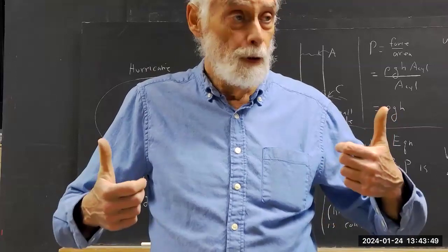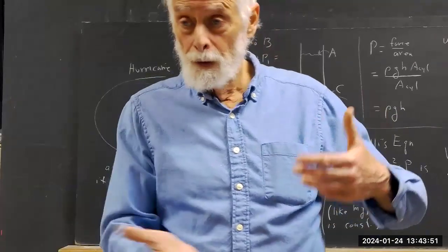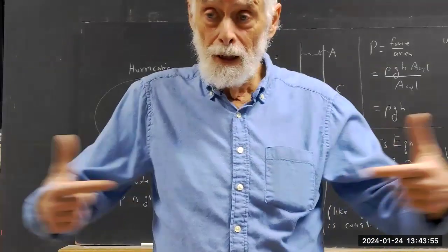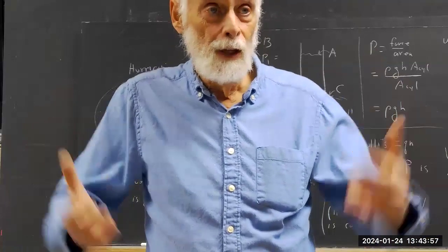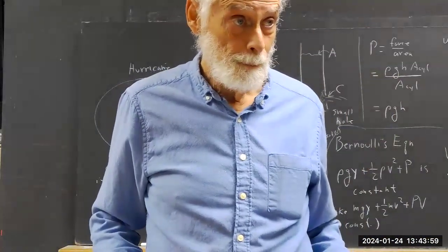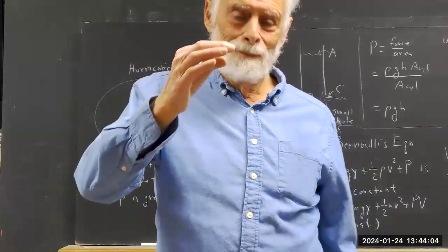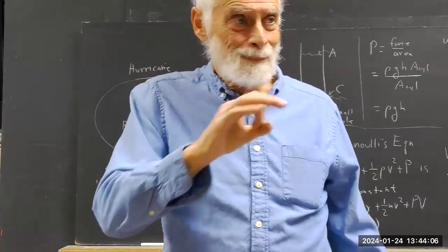Why is there a buoyant force? Because the pressure on the underside is greater than the pressure on the upper side. Pressure on the sides is perpendicular to it, so it does nothing to the vertical force. Okay. If you've got an irregular solid, well, you've got a bunch of little area increments.